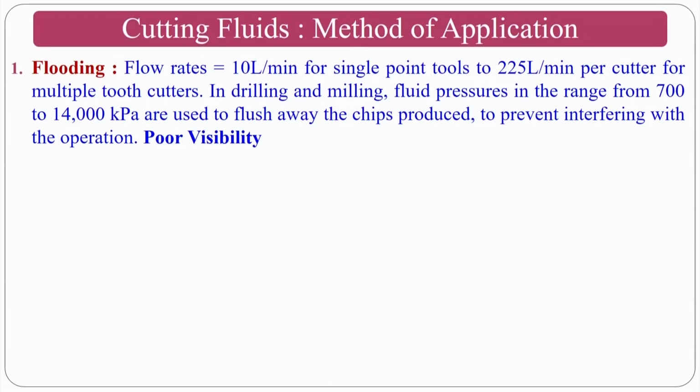Okay. So, normally for the methods of application of these cutting fluids, there are standard methods. One is flood cooling. Flood cooling you might have seen in the workshops, where you use a small nozzle and by virtue of gravity it will come, or you use a small pump so that you can pump it. The biggest problem here is the cutting fluid consumption is around 500 ml per minute. It's a huge amount of cutting fluid. That is why the cutting fluid cost is approximately 17% of the product cost.